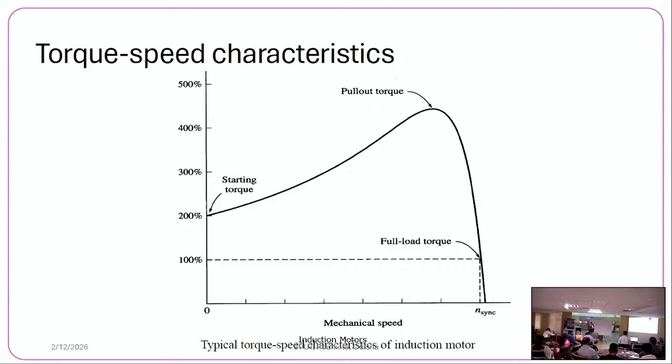If you apply more load torque, then only the speed will reduce. But in this case, whether load is there or not, we don't analyze that. Speed and torque are both increasing, which means it is drawing more power. From here to here, it is an unstable part which the motor quickly passes through.